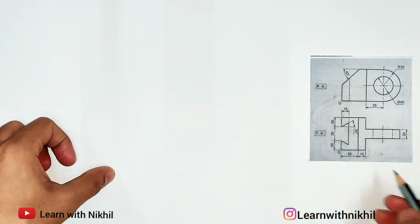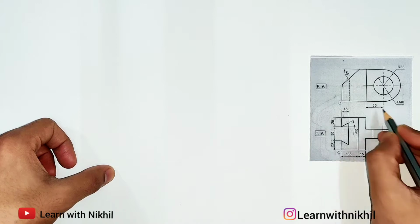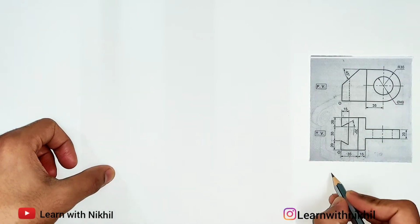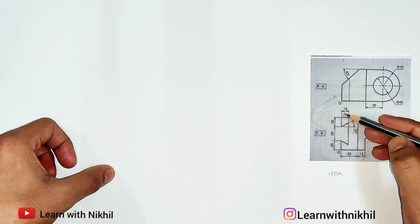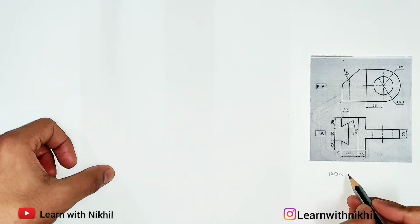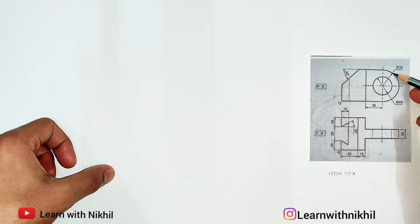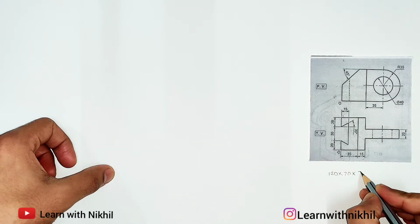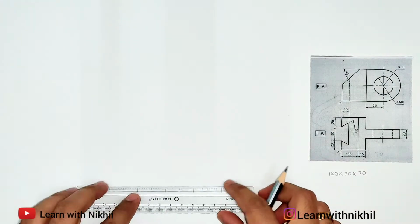maximum space. Next, the total width of the front view, that is 35 plus 15 plus this distance 35 and the radius 35, so the total is 120 millimeter. Then the depth of the figure is 20 plus 20 plus 30, that is 70, and the height will be the diameter of the entire semicircle, that is 35 plus 35, that is 70 millimeter. So as we have got the three dimensions, now using these dimensions we will plot the rectangular box.